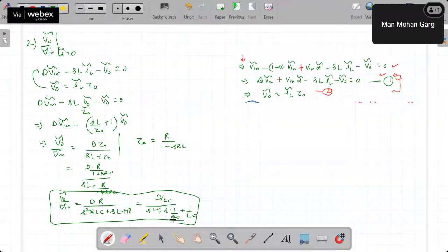If there are more than 2 modes, then we will get the linearized model for each switch, its current and voltage. Now we replace that switch by its linearized model, either voltage or current. Then once it is replaced by its linearized model, we can get the overall large signal model, and then the same process again, DC model and AC model, we can segregate it.